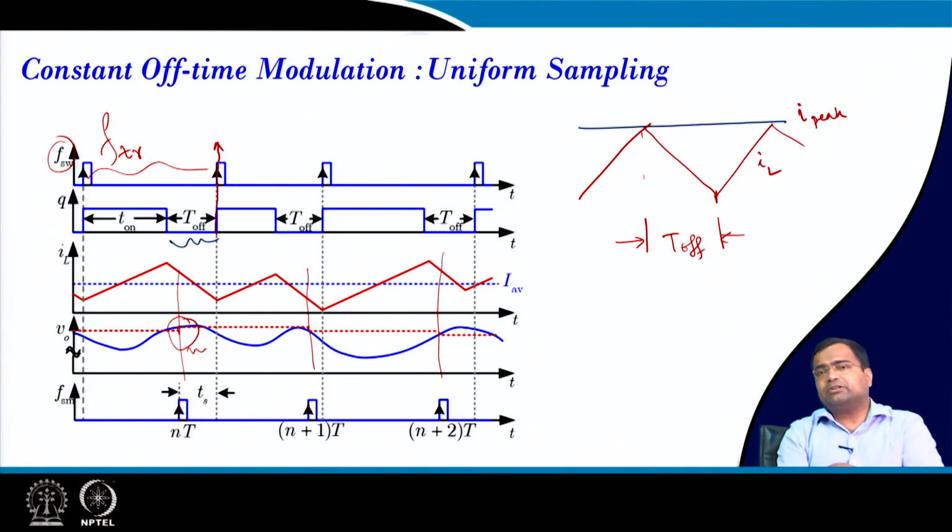Sampling period and the switching period, there will always be a variation, and we will see such control when you implement it in MATLAB. It will lead to something called multiple limit cycle oscillation, and that is not desirable because there will always be a mismatch in the timing. But how to reduce that effect?